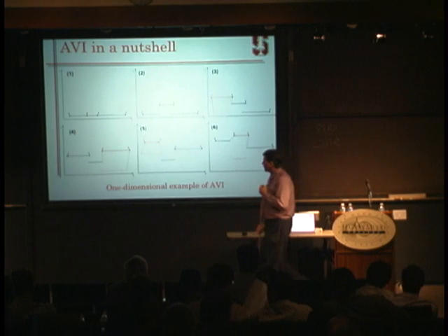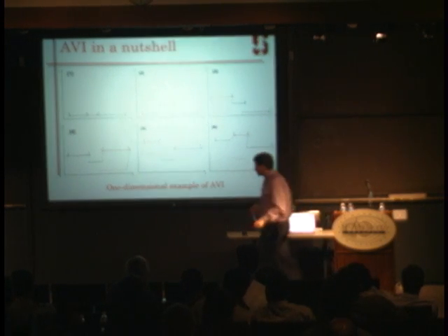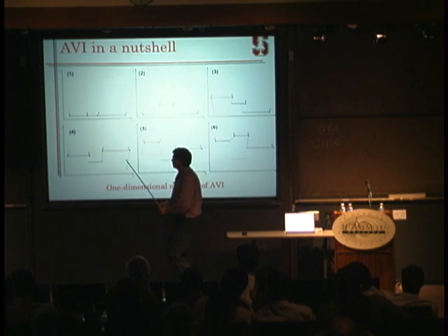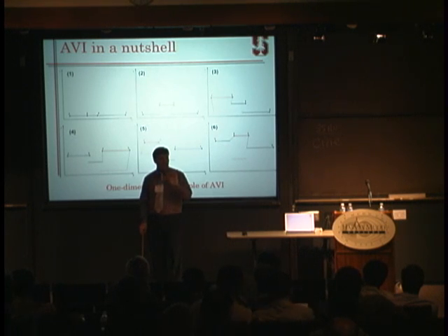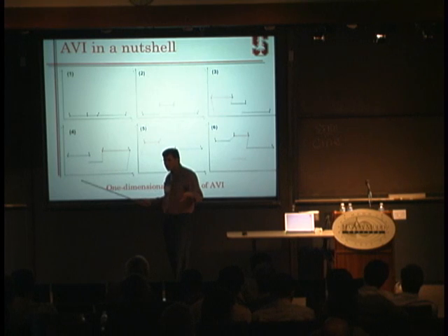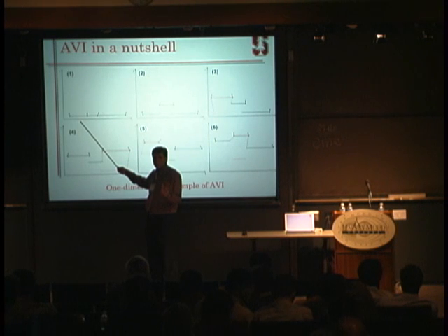So this is how the algorithm works. This is really the mechanism of how you do it. And this is very simple. This is done with a one-dimensional elastic bar, where you have 3 elements and 4 nodes. So for all practical purposes, if you don't know finite elements, this is just a mass-spring system where the springs are nonlinear.